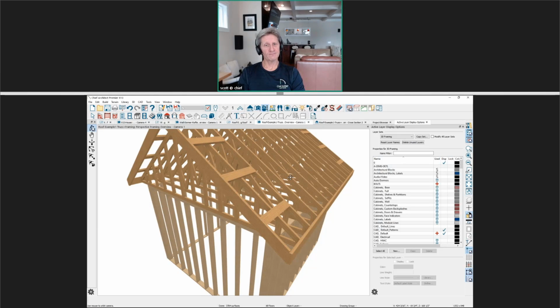When you were showing the truss base, because it was an addition, you extended your truss base out to include the eave overhang of the trusses. If you're doing like all new roof, you just bring that truss base to the end of the wall, and then the tails don't show, right? Right.